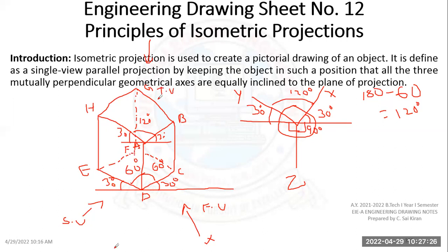So in this isometric projection, if I'm taking an equally inclined angle of 120 degrees between the axes X, Y, Z, then I can see the three sides clearly. I can see the complete front view, my complete side view, and my complete top view here in this case. Okay. Then in the question they'll be asking, from the isometric position, draw the vertical position and horizontal position.